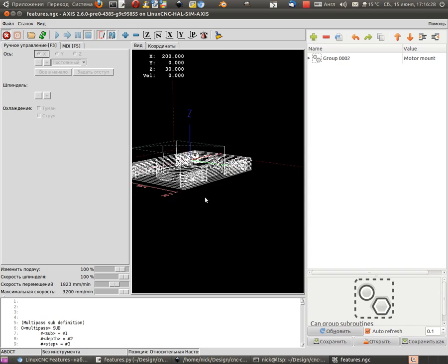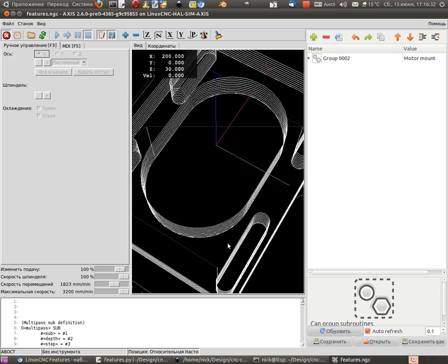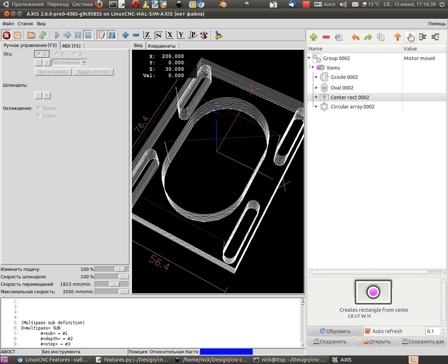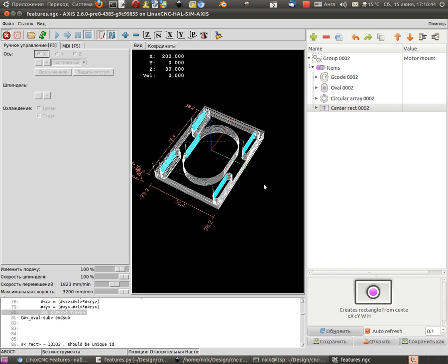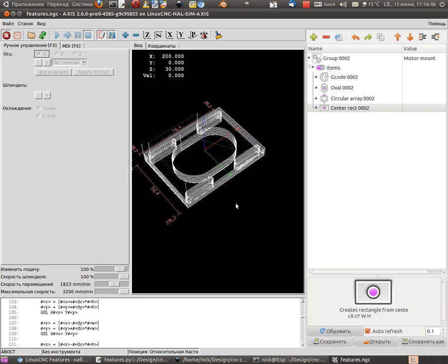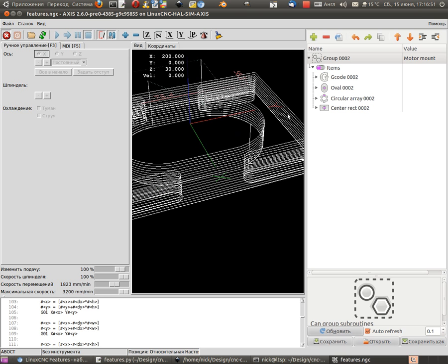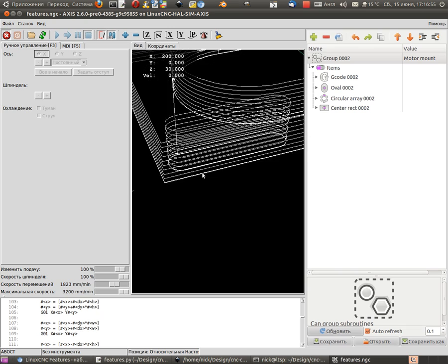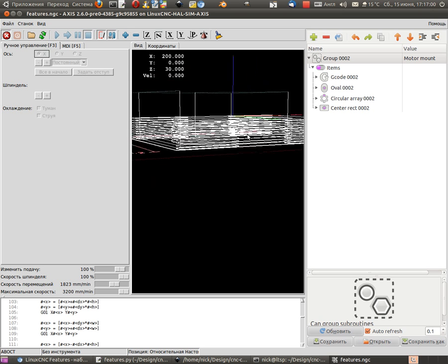As you can see, we have multi-pass cutting over this mount. Oh, by the way, we should put our rectangle at the bottom because it will cut out the whole plate. That should be at the end. So we can adjust the parameters of the depth on each pass, or for example the final cut, or any others, like rapid distance.